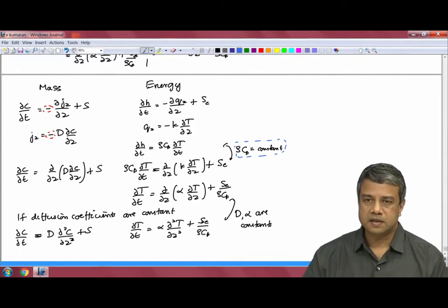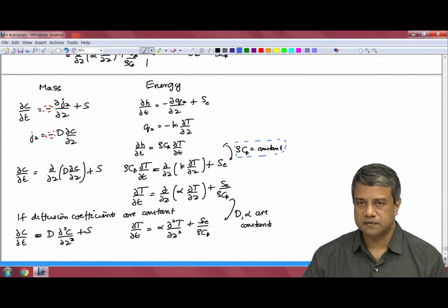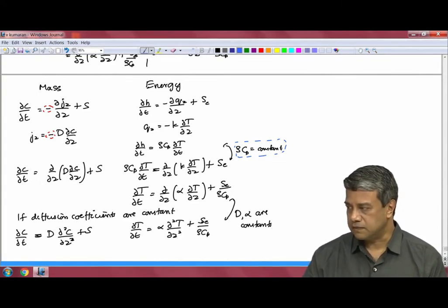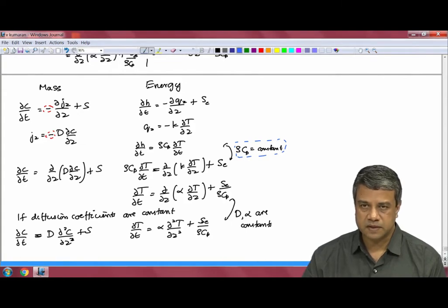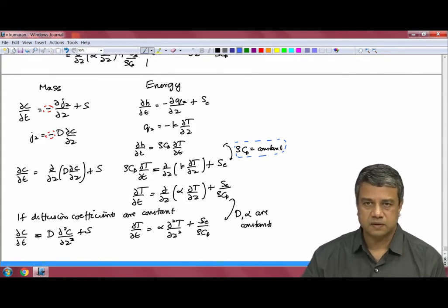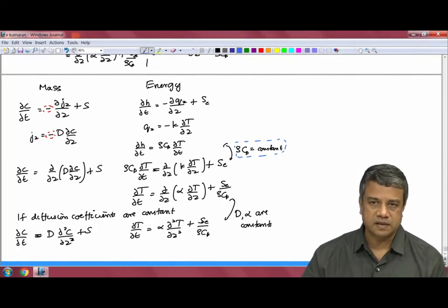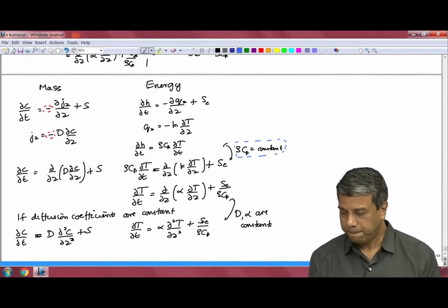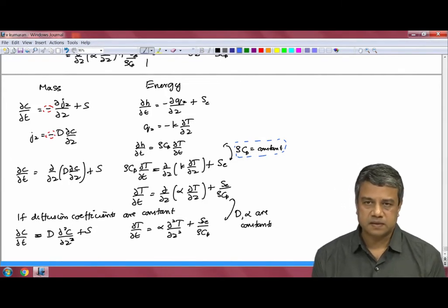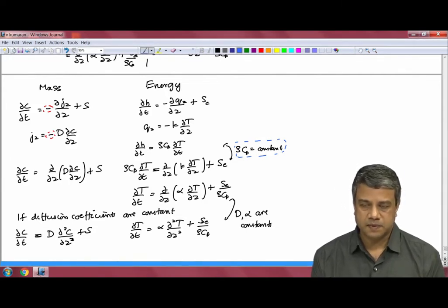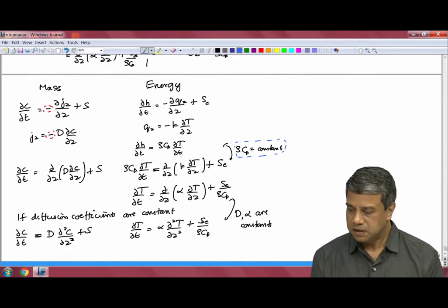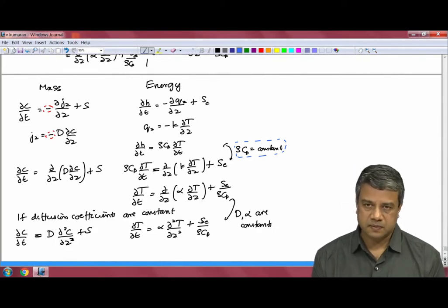A fluid can be considered incompressible if the flow velocity is much smaller than the molecular fluctuating velocity or the speed of sound, because density variations in the form of shock waves travel at the speed of sound. So long as the flow velocity is much smaller than the speed of sound, the density is a constant, and the specific heat is actually a constant in many situations.